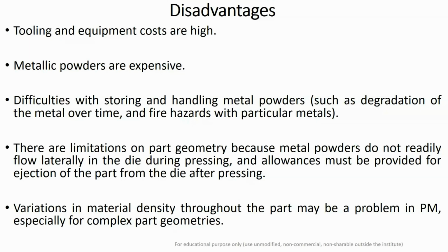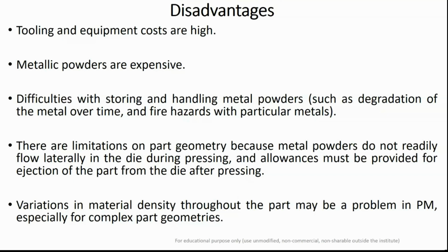Consider the case when the powder is not flowing efficiently into the die cavity and you are applying pressure on this powder mass. What happens is that at some places the powder gets consolidated at different locations, while elsewhere it will still be in powder form. Such parts will definitely fail on ejection from the die. And during the consolidation they have the tendency to stick to the die cavity as well as the upper and lower punch.